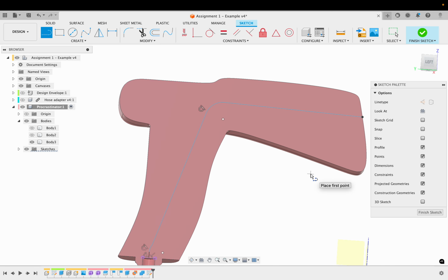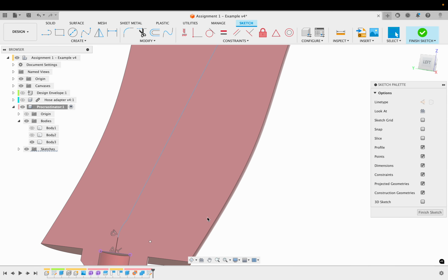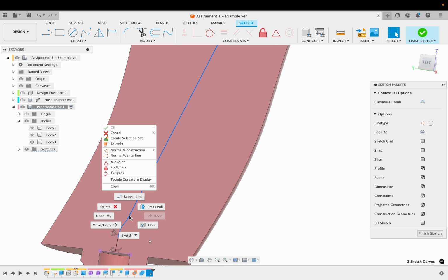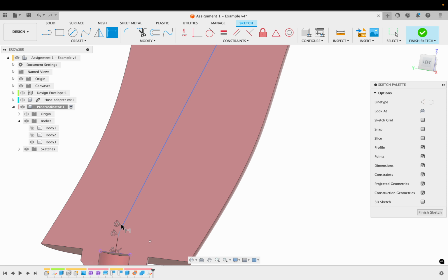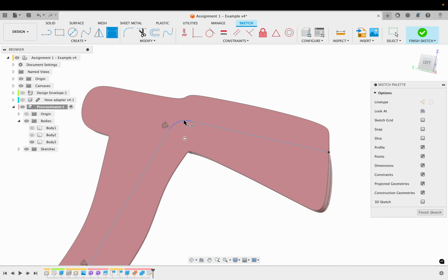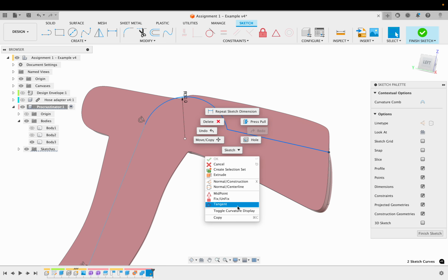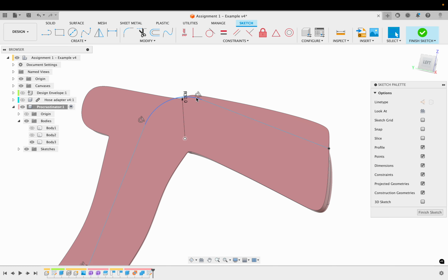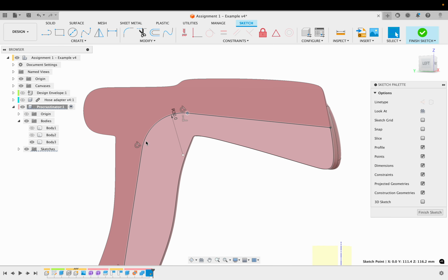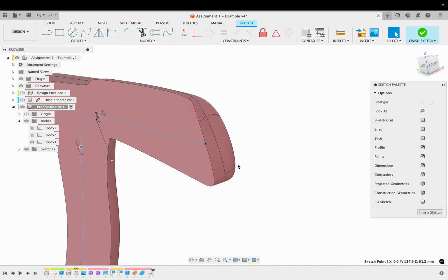Okay? And then I'm just going to constrain this. So I'm just going to, let's see, that's tangent. That's a 10. Maybe it's more than a 10. Maybe it's 30. Okay, so now I got my water channel, right? This is not fully constrained. You can see the lines are blue. Typically, when you do stuff, you want fully constrained lines.